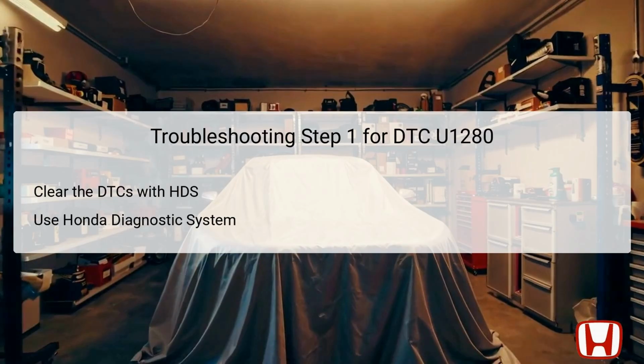The first step in troubleshooting DTC U1280 involves using the Honda Diagnostics System, commonly referred to as HDS. Begin by clearing any diagnostic trouble codes stored in the control units. This step is essential as it resets the system and allows for a fresh assessment of the vehicle's electronic components. After clearing the codes, it's crucial to verify whether the U1280 code reappears. This initial step helps focus subsequent diagnostic efforts on confirming whether the error is persistent or an intermittent fault that may have been previously logged.